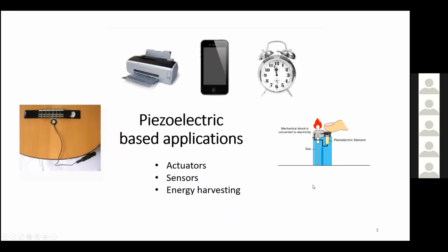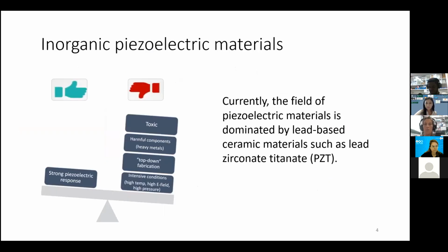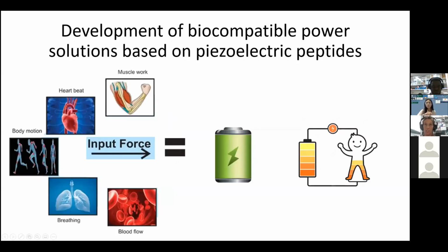Piezoelectric materials and applications based on the piezoelectric effect are all around us in our daily used applications and devices. They can be used in actuators, sensors, and energy harvesting. Currently, the field of piezoelectric materials is dominated by lead-based piezoelectric ceramic materials such as PZT. However, although showing a very strong piezoelectric response, PZT is toxic and entirely non-biocompatible, creating the need for alternative piezoelectric materials with strong piezoelectric performance, especially in the field of bio applications.